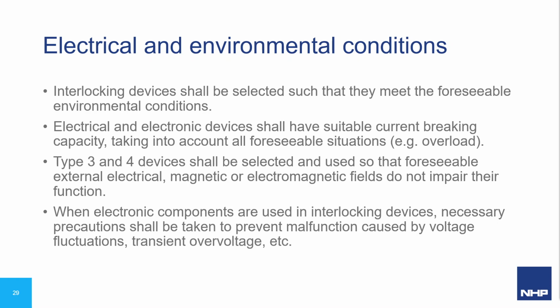For electronic devices such as Type 3 and 4 switches, make sure that there is adequate protection against the effects of electromagnetic interference. Make sure everything is sufficiently earthed. Run the control wiring separate from the power wiring. If there is a VSD nearby, make sure its output is using shielded cabling, etc.